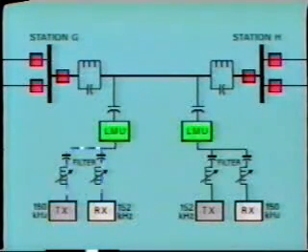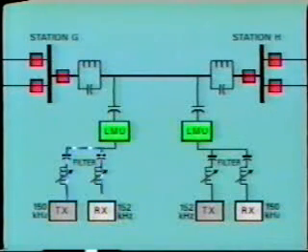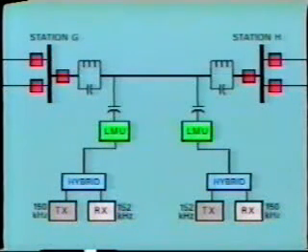Even a very weak 150 kilohertz signal may interfere with the incoming 152 kilohertz signal and cause misoperation. In order to reduce this loss, the transmitter and receiver at each end are coupled through a hybrid unit before connection to the tuner and coupling capacitor.